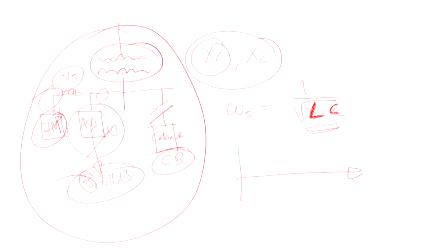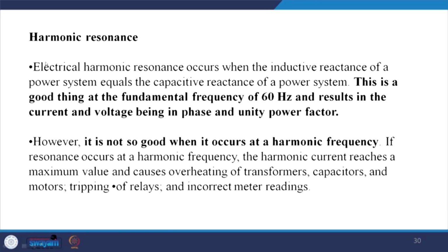So, this is a very big disadvantage of this capacitor. Let us go back to our discussions. This is a good thing at the fundamental frequency of 50 or 60 hertz, and it results in the current and the voltage being in phase with the utility power factor. That is a good part of it, but the worst part is that it may cause harmonic resonance.